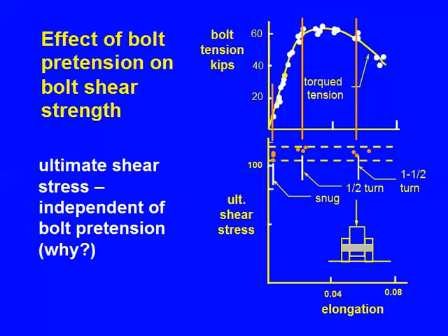So you put the nut on, you turn the nut, that's called torquing or applying the torsion. The bolt elongates, it develops a resistance. At some point that curve turns over like that. Okay, that's just almost common engineering sense. So we do those little shear type tests down in the lower insert. And let's suppose, for sake of argument, that we put on a half turn of nut. That's going to be one of our standard installation procedures. So let's fly a line in to the half turn.